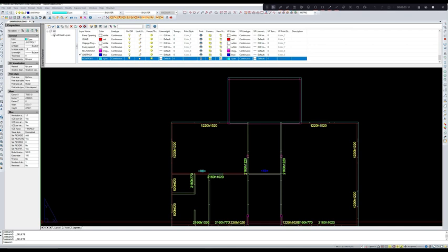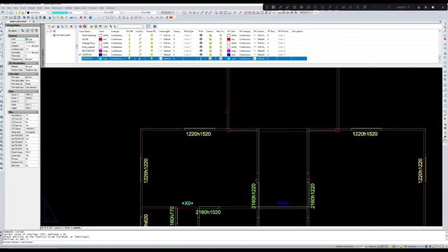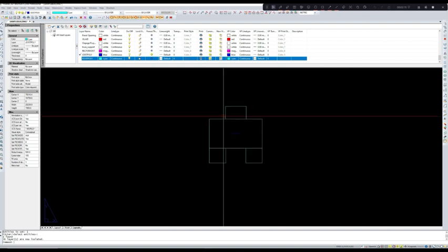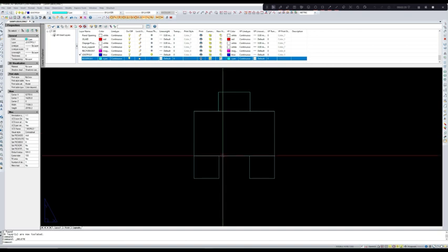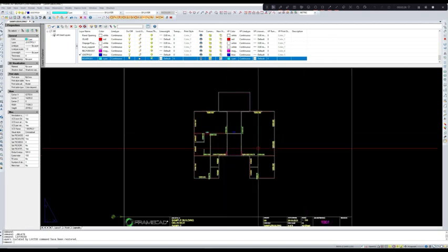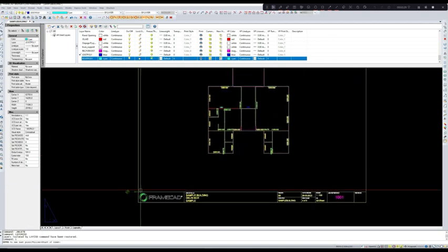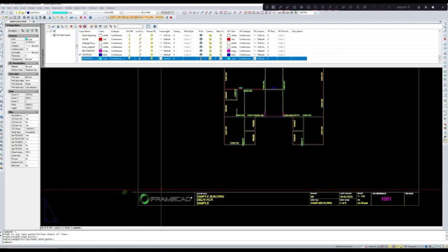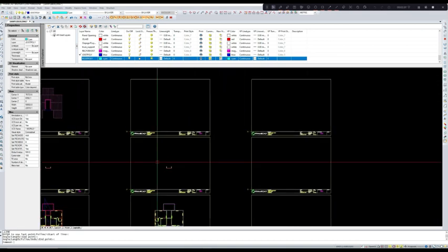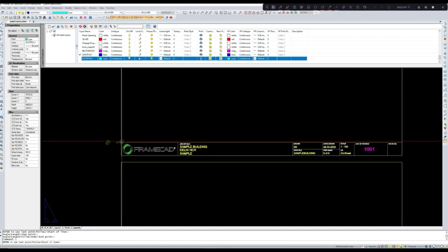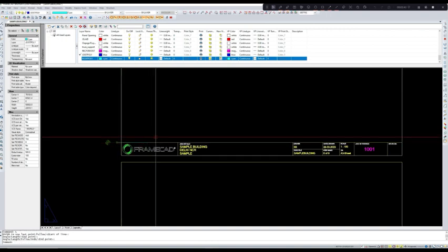Now let us go to the command bar and write LAYISO. Select this newly created rectangle. So before that, LAYON ISO. We'll need some reference coordinates as well. So let us draw a line here. Again, draw a line here. Again, draw a line here. Again, draw a line.